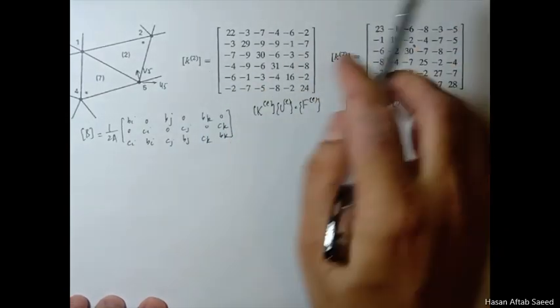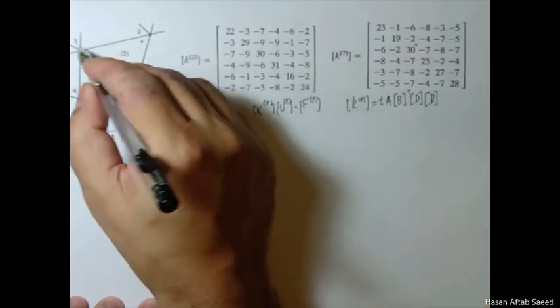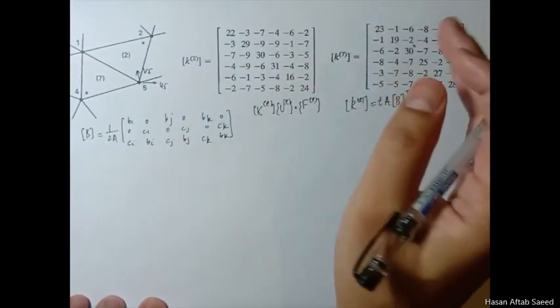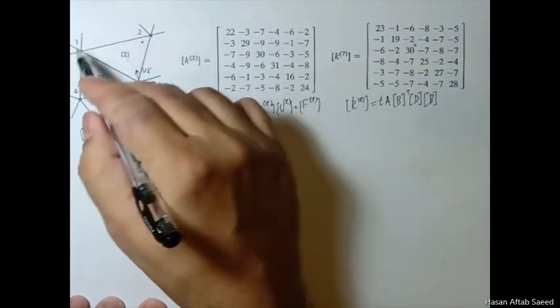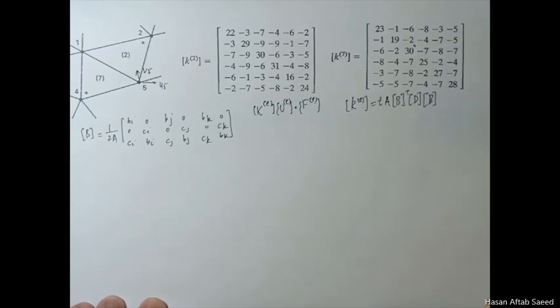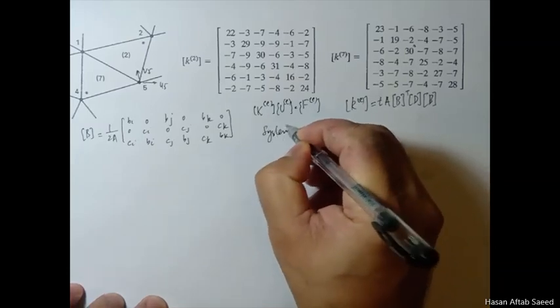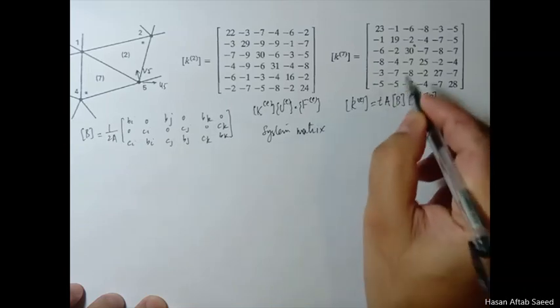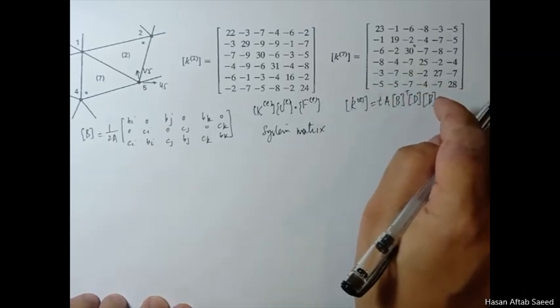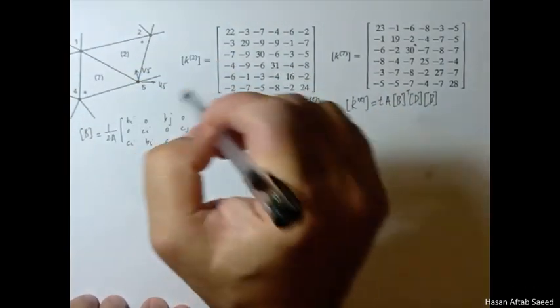So we are not going to calculate Ks from data given, although in this case we cannot, because we don't have the values for coordinates, but for any problem you'll have those values. So to calculate these two is not difficult. Now if we have these two and we want to assemble them in a global matrix, what should we do? That is the topic for today. So we need to assemble the system matrix, not the elemental one, but the system matrix. Now we'll just illustrate using these two elements, but you understand that there could be other elements also.